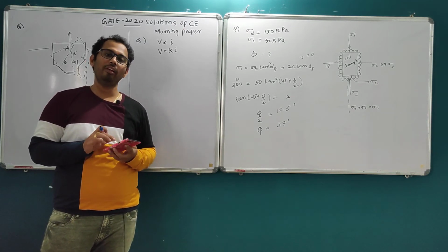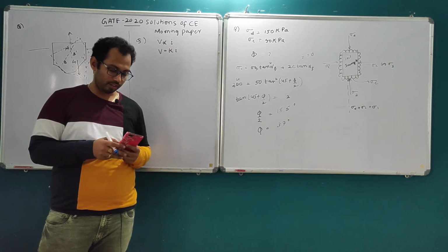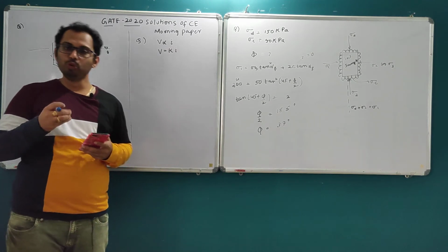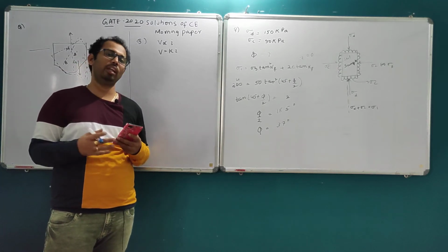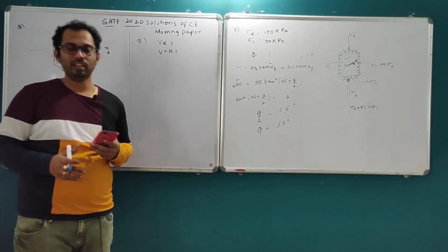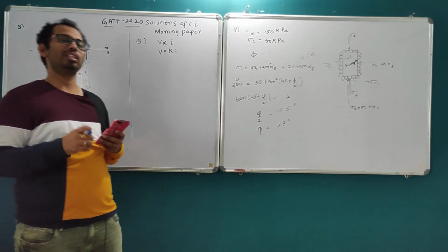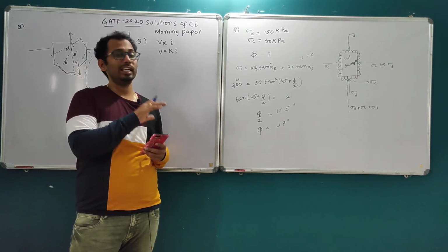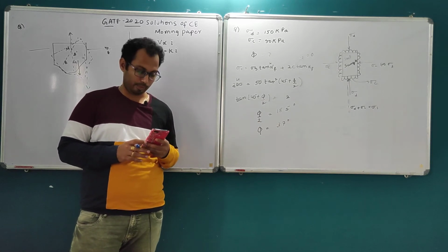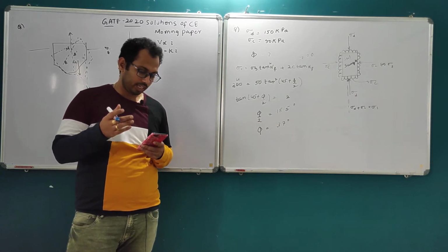It will have only laminar kind of flow because the velocity is very less. The water has to move through the pores of the soil particles, so that is why generally the velocity is very less. So we can safely assume that the flow inside the soil strata is laminar. By assuming that only, Darcy derived Darcy's law, V is proportional to i. So that is the statement.